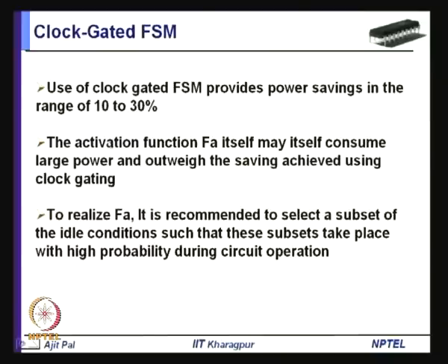So, this power saving that you achieved with the help of this clock gating FSM may be outweighed by the power dissipation of this activation circuit which generates FS.